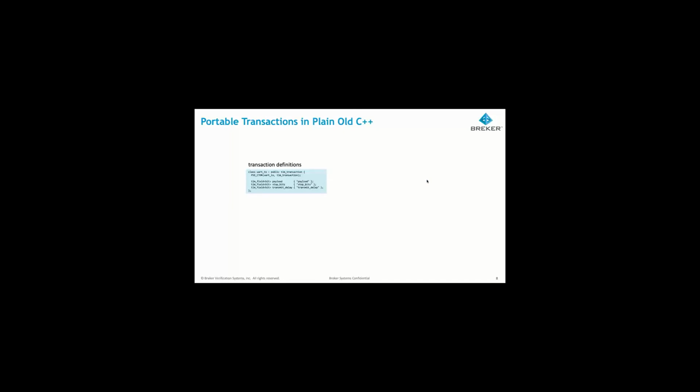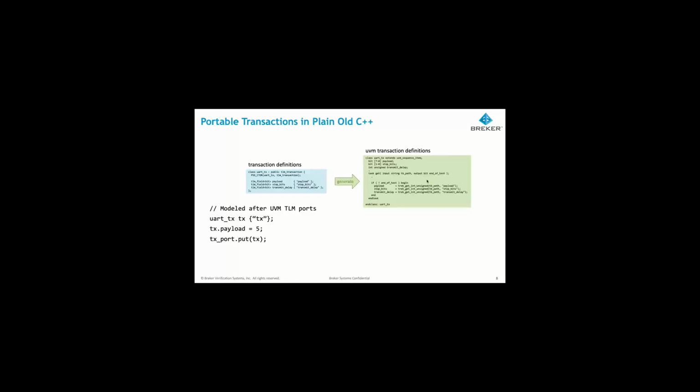leveraged. Same thing for transactions, where we need to not only be able to drive a processor with software in these tests, but we need to drive the I/O, and we can use TLM type mechanisms, again using common standards, and actually drive this through the OS, and the end user does not have to worry about trying to, at the bare metal level, set up transactions and ensure that they're all executed correctly. This is all done automatically.